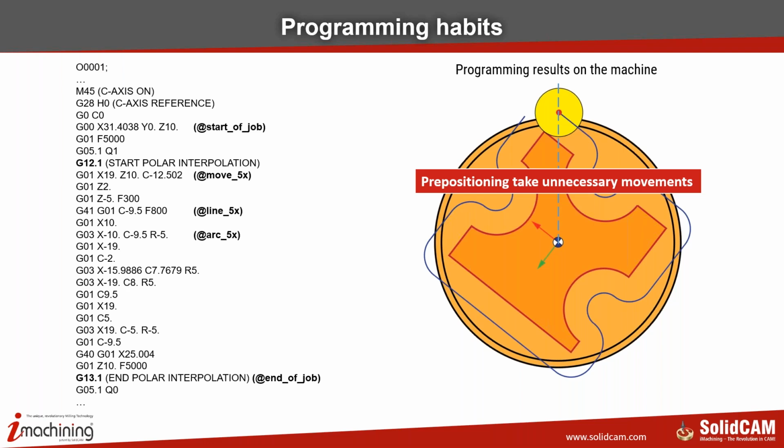So what is all about? As you know, in this particular part, I have constant movements. So the constant movements will be in most of the cases completely fine. But for example, if you want to make this line here first, and then second line here first, then third line here next, you will receive many rapids.